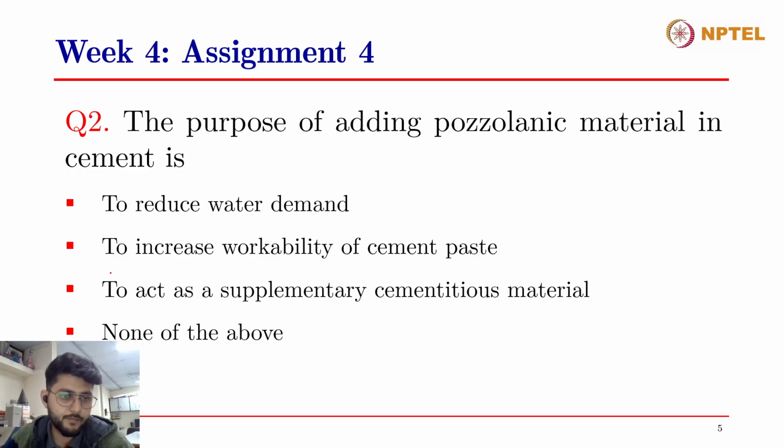All right, that is pretty straightforward. We've already discussed it. It is to act as a supplementary cementitious material. This is the correct answer. Pozzolanic materials are also called supplementary cementitious materials, meaning that they supplement the cementitious reactions. They produce additional hydration products which contribute to the strength and durability of the cement and concrete.